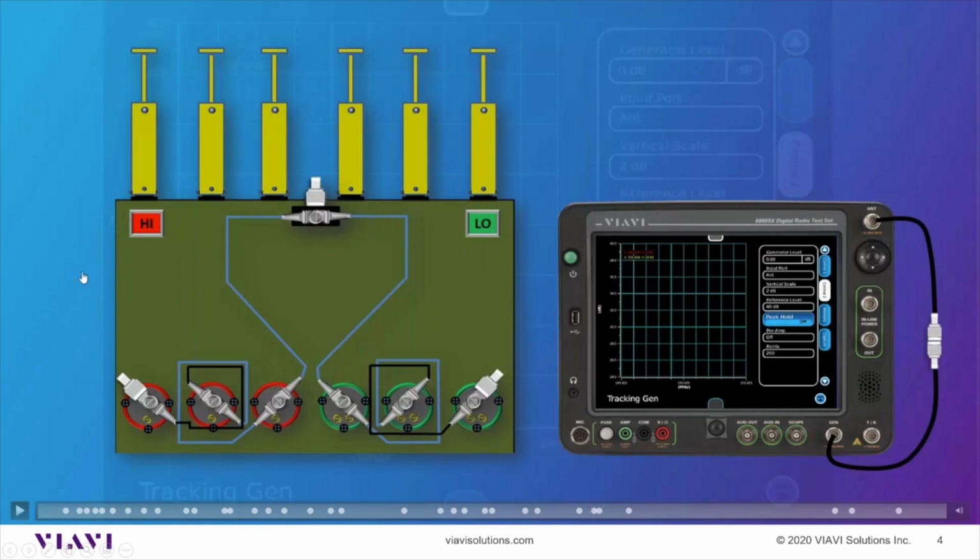Just for an example, for folks that are just learning about duplexers, let's say we've got a 100-watt transmitter out here, and it's going to be coming in this first resonator cavity, and it will resonate and get picked up by the pickup loops, and then be transmitted to the second resonator, resonate in that cavity, and then be picked up by the loop and transmitted out to the third cavity, and then out the antenna port through our transmission line and then out the antenna.